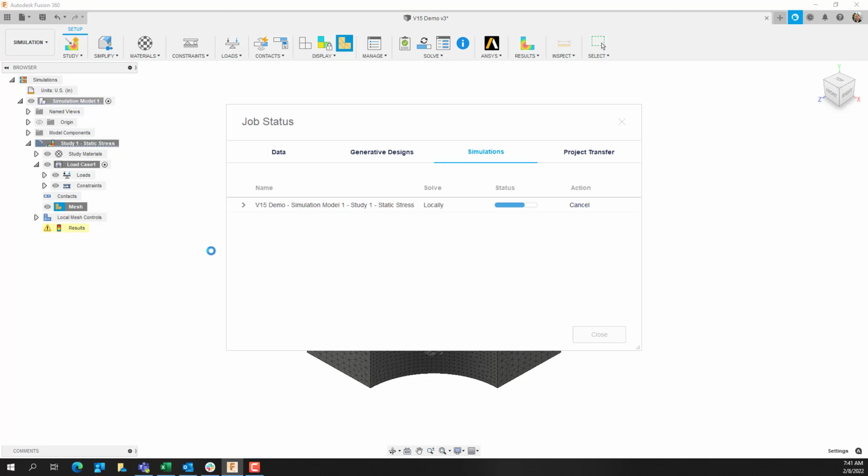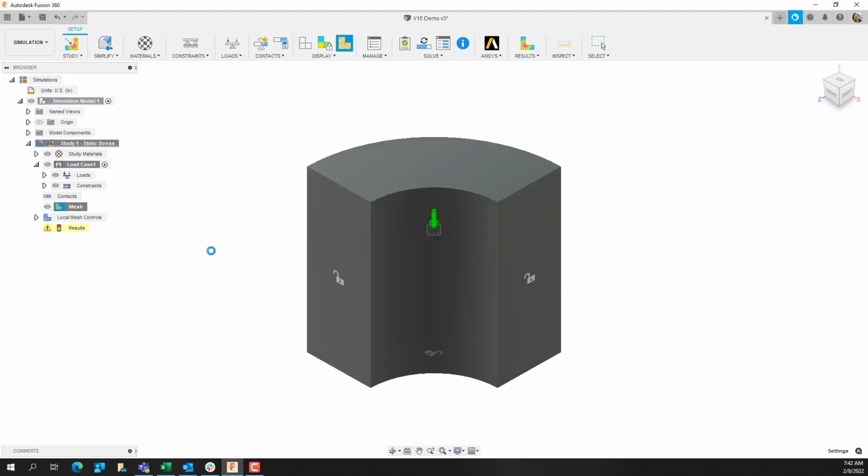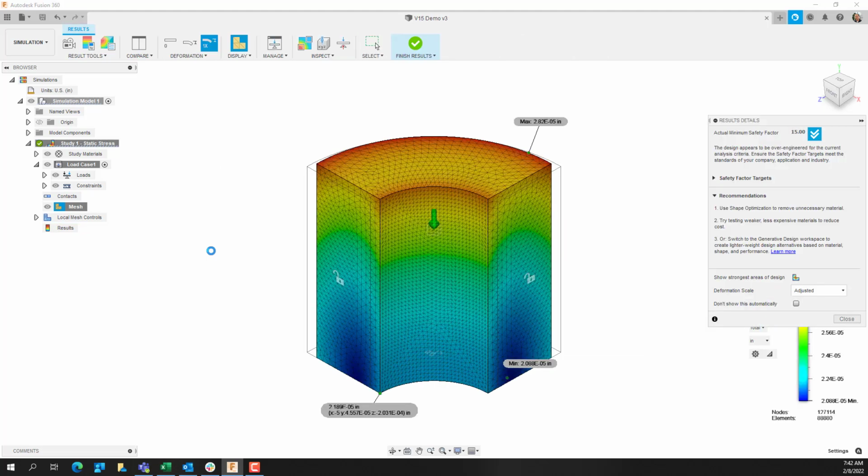That is, when I change the mesh size, I'm not seeing drastic changes in what my output is. So generally, when you hear about mesh convergence or converging upon your results, you would do 3 different runs in order to make sure that your model is converged pretty well.